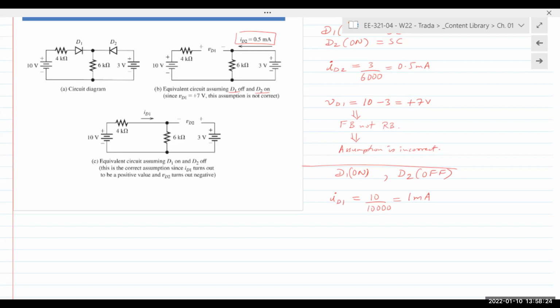And now, E2, same thing on the other side. Anode for D2 is at 3 volts. Cathode for D2 is at 6 volts, right? Voltage divider. So 4 volts across here, 6 volts across here. So cathode for D2 is 6 volts, anode is at 3 volts, meaning the difference in potential is 3 volts. Cathode for D2 is 3 volts higher than the anode. I will repeat the analysis when I write it down. But cathode for D2 is 3 volts higher than the anode.